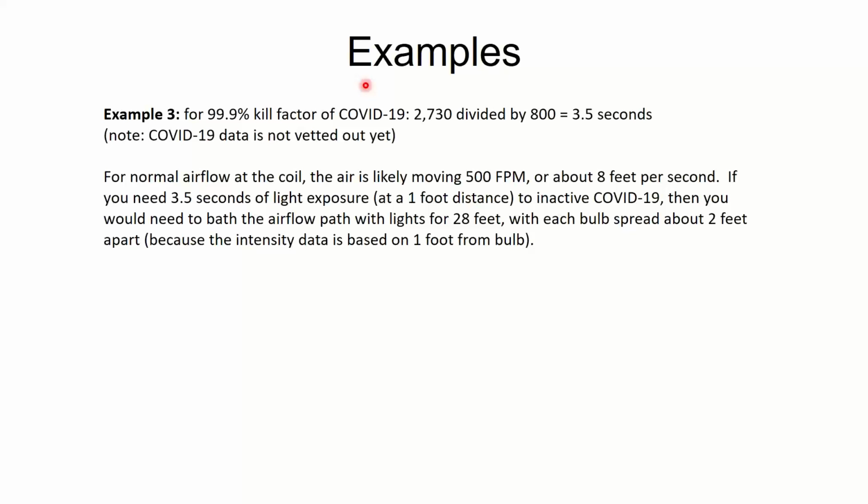But what are the chances of that virus going around the building 3-4 times? We already explained how difficult it is to get the virus entrapped in the air to begin with. If I got it to the UV light once, I'm already feeling like I did pretty good. Chance of doing it multiple times is pretty low. So it is what it is there. You're not going to be killing germs in your building with a UV light mounted in your air handler. You're just not. You'll kill some, granted, but it's not enough that it makes it interesting in any way by itself. So what the hell is the UV light for?